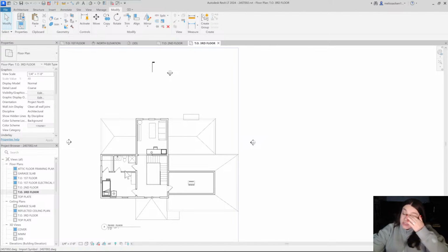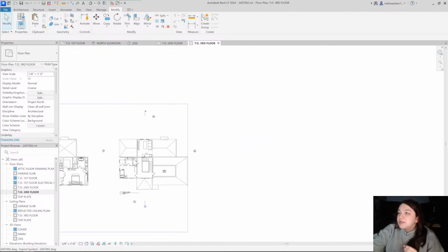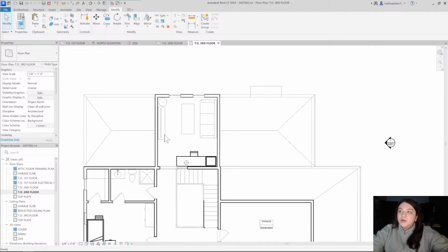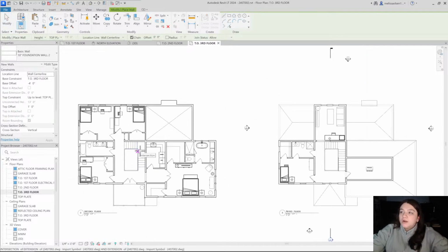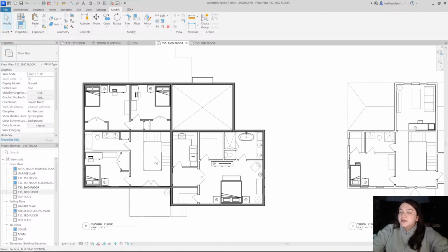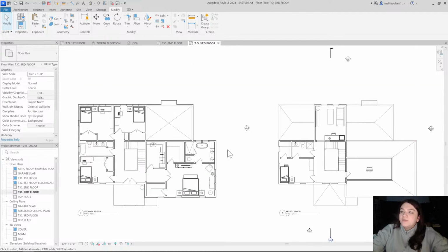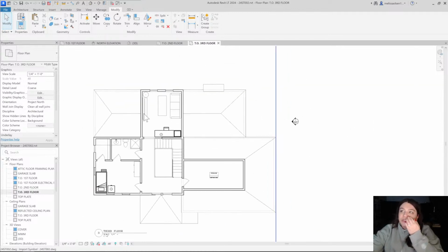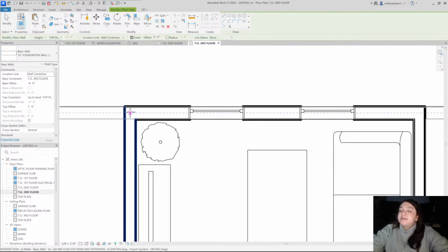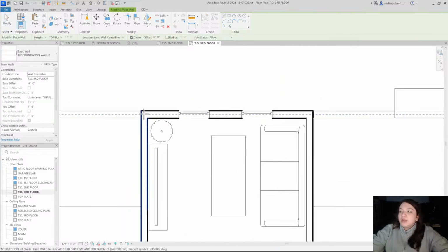So how I'm going to do this is I'm now going to draw the third floor walls, because if we go to the second floor, we can see that all the exterior walls from the first floor are just going straight up. So we're good there. For the third floor, that's when things start to change. So we can see that we're closing off the space below with some roofs, and we're actually adding in some new exterior walls here.